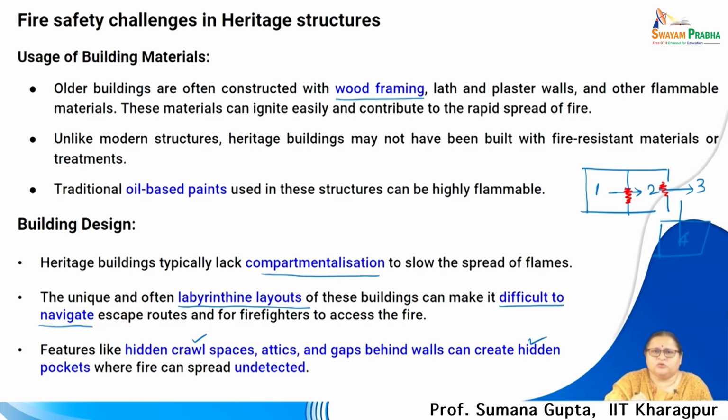So, when a heritage structure is revisited for fire safety or fire prevention retrofitting planning, all these kinds of spaces should not be neglected or kept out of scope, because these are the points from where fire can move from one space to the other. Needless to say, we had discussed this at length for services plans.